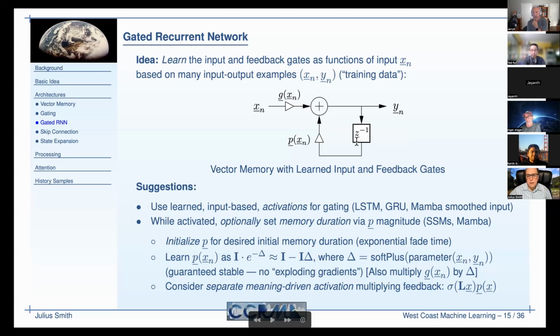Ah, yeah. It starts out as a scalar. Now it's an array of unit sample delays. It's just a vector delay. So here's where everything gets summed, and then we have to take that sum and hang on to it so that we can add it to the next incoming vector. Then we get a sum of everything we had before plus the new thing. So this is just saying delay it to the next time step.